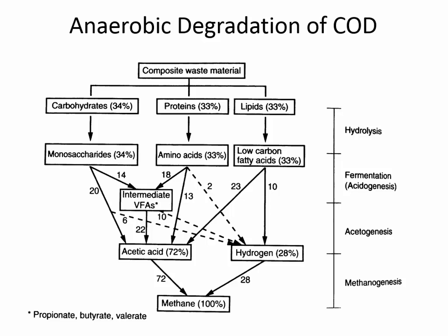So hydrolysis is where the three primary energy sources are broken up into simpler components. Typically in wastewater, there is going to be some fraction of it that exists as carbohydrates, some proteins and lipids, and actually all three of those constituents can be eventually turned into methane. The carbon in all three is going to be transformed through, first, hydrolysis, which just means the wetting or the breaking it apart. Fermentation or acidogenesis is where monosaccharides and amino acids are forming.